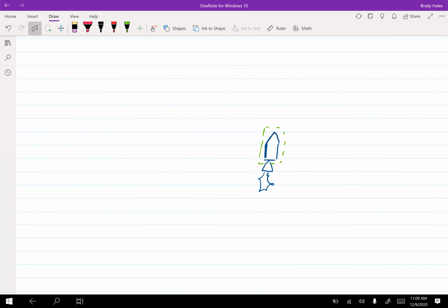Well, space is a vacuum, so there's no convection and there's no conduction happening, at least what we're considering here. There's no conduction happening across the boundary. Obviously, there's some conduction on the inside. There's temperature gradients between walls and insulation and tanks and stuff, but let's just look at the surface temperature of the rocket, right?